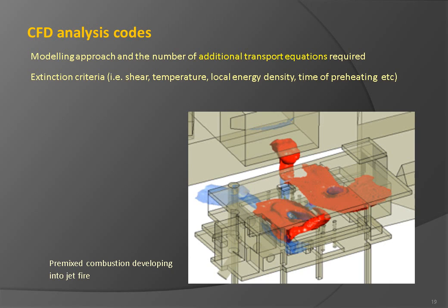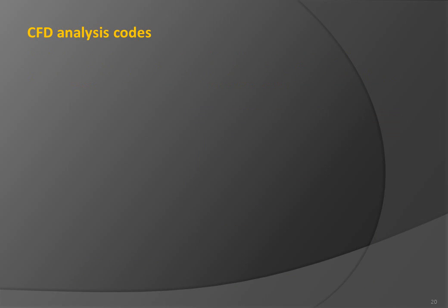This allows capturing the wall boundary layer effects where most of the momentum and heat transfer takes place. The figure below illustrates the immersed solid method that simply blocks the flow in the cells where the solid body appears. In most cases, such simulation domain crudely follows contours of the solid object, making the resolution of the boundary layer impossible.